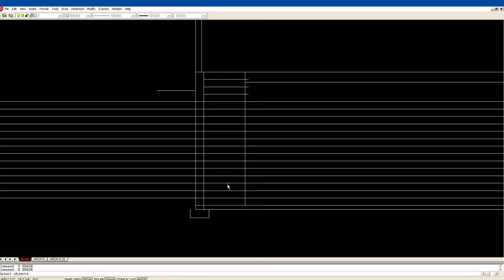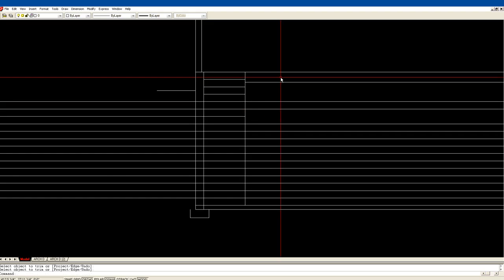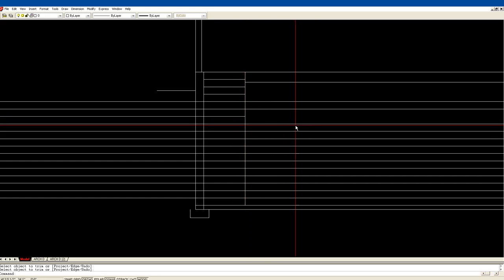Let's erase, only this time we won't go right to the top of the line. Just like that. So again, we've got four risers, 1, 2, 3, 4, top of landing. This one's a dividing riser, and then this one is where we carry on with the stairs. So I'm going to trim this. Don't let me get lost here. Now this is our first riser down in the other direction.